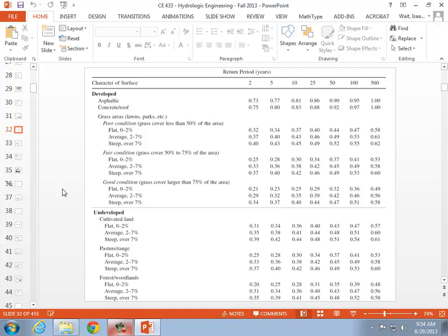And plants usually help infiltration, where bare earth isn't as good as plants, because a grassy area, for example, having the roots penetrating down into the surface sort of provides a pathway for the water to get into the ground. And so, my C value of 0.6 for the rail yard, 0.5 for the housing, calculating that composite C, those are guesses, and I wouldn't say that a different guess was wrong or right necessarily.